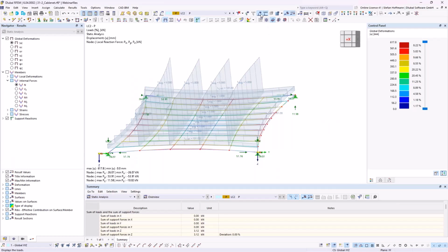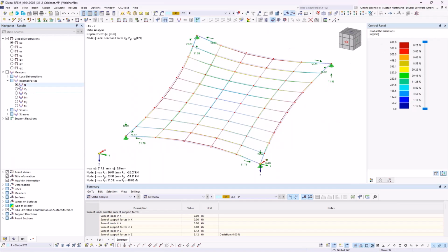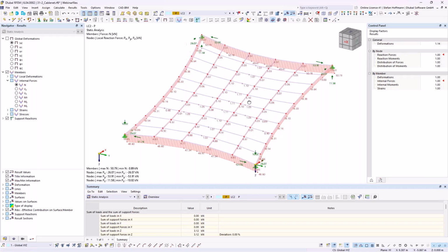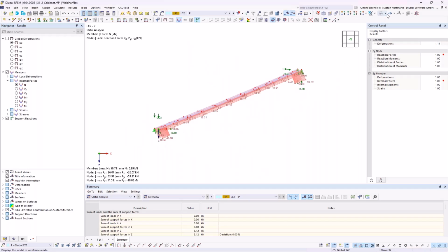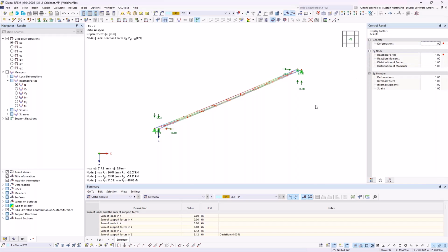So you can see we now have, with the 5 kilonewton meter in this direction, such a shape where we can quickly investigate the normal force distribution. So we most likely reach 5 kilonewton in this direction and 1 in this, and all the others are identified by the geometric boundary. If we would now like to observe the deformation, we can check it like this, and the best thing is to scale it for 1.